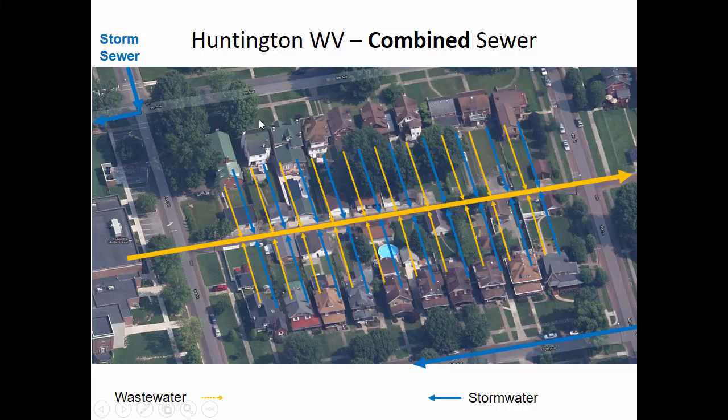Well, if you think about the storm drains and where they're going, each of these homes would have a roof drain and a foundation drain. And so rather than having the stormwater from the roof go into the yard, which would be preferred, many of them have a pipe from the roof directly to this wastewater pipe. And so the sewage isn't going to make it up to the roof. It's just going to go to the lowest point of relief, so the lowest elevation where there's just empty space the sewage could go to. It's usually a basement.